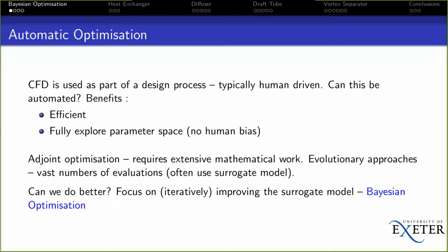And over time, this process, generation by generation, explores your parameter space very effectively in multiple dimensions, and can find the global rather than the local maxima or minima or optima, basically. The advantage is you don't need to do the mathematical background work, but you do have to do a potentially vast number of evaluations, which, if your evaluation of the fitness involves running a CFD model, can be extremely expensive. In fact, we very often apply this by way of a surrogate model.